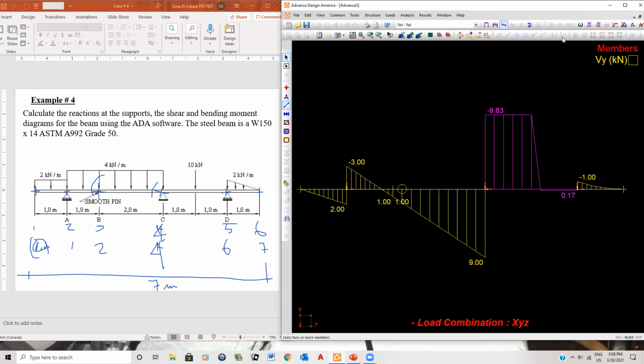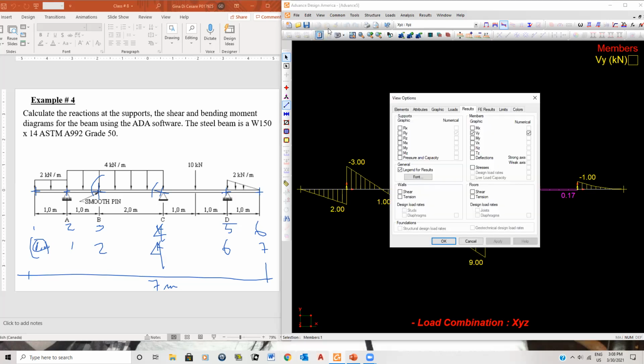and I don't know if you guys remember, because I have a triangular load here on the shear diagram, this is parabolic, and it drew for you parabolically here, okay? So that's what it is. A triangular load on the shear diagram is parabolic, and on the moment diagram, it becomes cubic. You don't really see the difference because they're very similar curves, but this is parabolic on a shear and cubic on a moment diagram. So there's my shear diagram, and of course, ultimately,